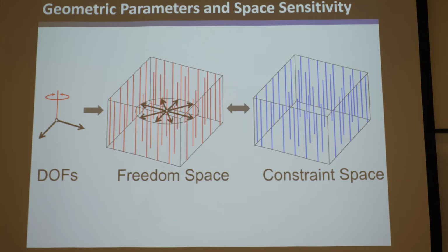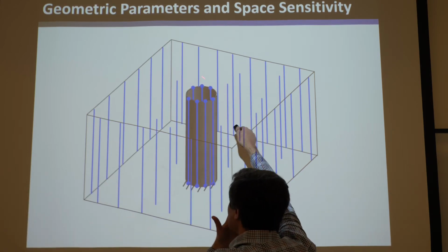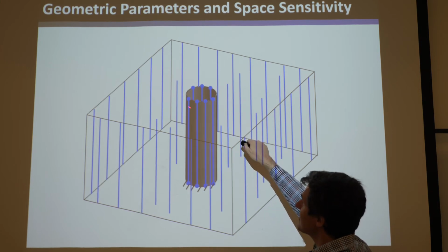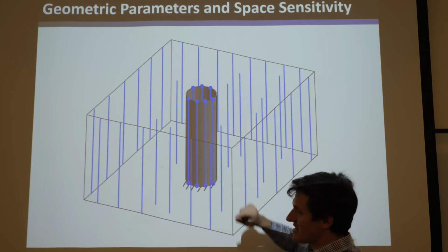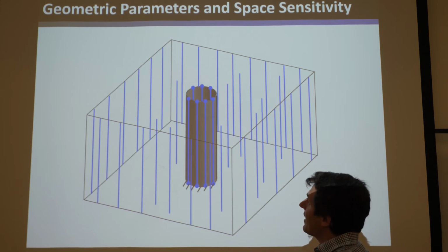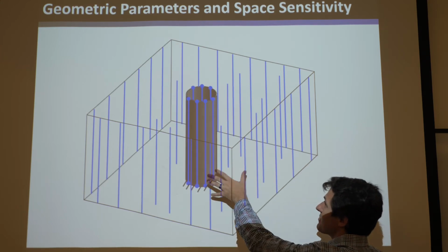All right, so I'm going to give you an answer. Okay, there's, of course, infinite element geometries that would work, but one is just a hollow, infinitely thin cylinder. Okay, because if this is hollow and infinitely thin, and you connect the ground down here and the stage up on here, then you can find blue lines that can connect those two bodies and pass entirely through it without exiting it. These are the parallel lines. And they do lie within this constraint space. And there are at least three independent ones. They're not all on the same plane. And they can fill it, so the entire thing's blue. So it's a parallel element, and it lies within this constraint space.